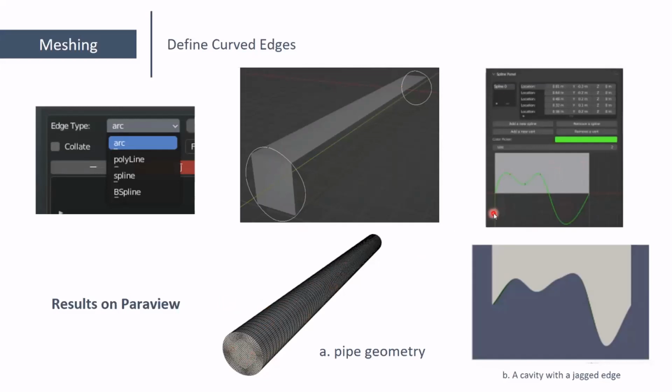Then we also have the spline panel. So the spline panel over here is essentially replicating the same thing with spline, but we wanted to test this out. Because normally, the methods that we were utilizing to replicate spline within Blender were not by default the same as that of OpenFOAM, because OpenFOAM very popularly utilizes the Catmull-Rom splines.